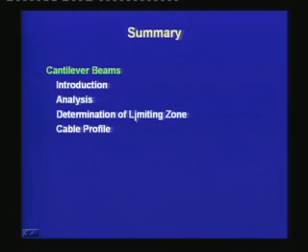In today's lecture, we covered the analysis and design of cantilever beams. First, we observed the different types of cantilevers that can occur. In a building, the cantilever can be a part of a continuous beam, but the cantilever extends outside the last support. If there is not a continuous beam, usually a cantilever is provided with a backspan to reduce the torsion in the supporting column. In bridges, there can be cantilevers in a balanced cantilever type of construction. That means over a pier, two cantilevers are progressively projecting out during the construction.